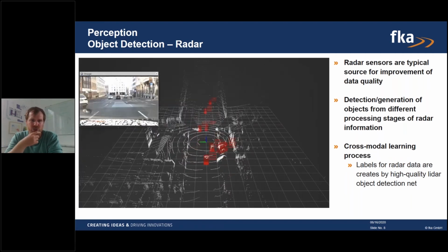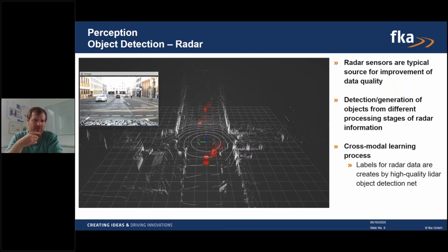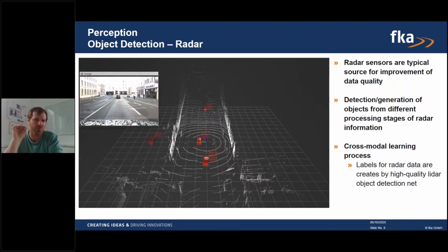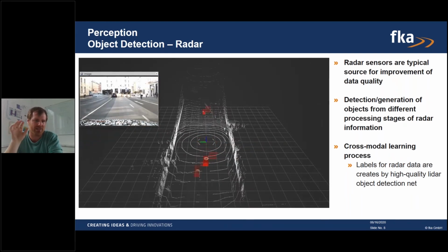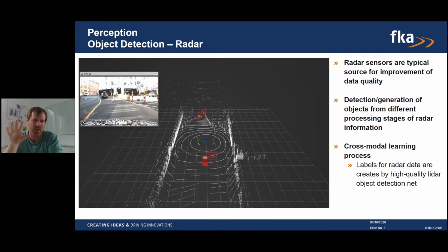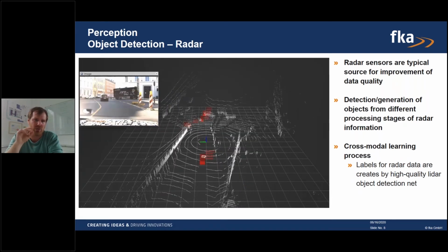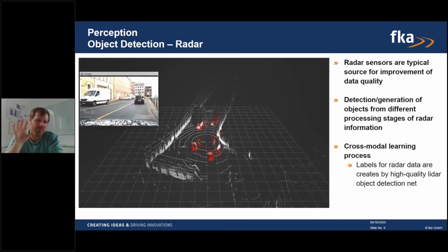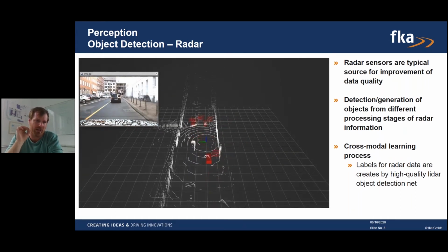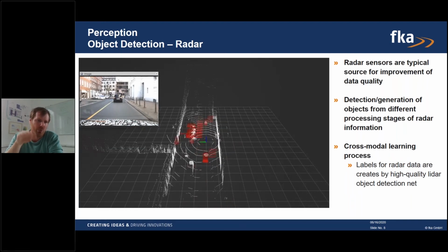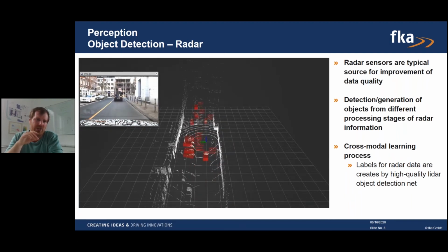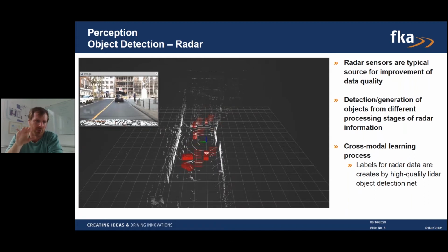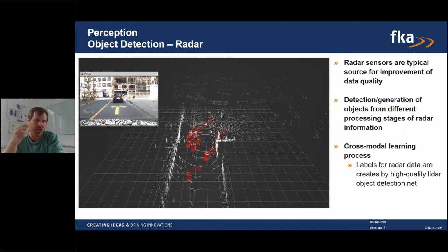So we have the two sensor systems deriving data, looking from different perspectives at the scene, since they're mounted at different heights and everything. You maybe just saw in the video that for radar, even if they're mounted correctly, they can sometimes see, I would say, through the lead vehicle, because they bounce on the ground and see the vehicle in front of it.